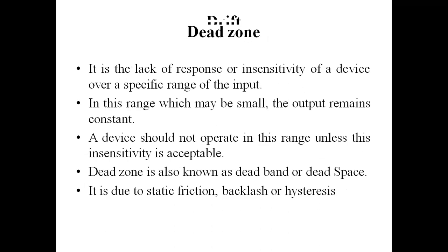The next one is the dead zone. What is dead zone? It is the lack of response or insensitivity of a device over a specific range of the input. In this range, which may be small, the output remains constant. A device should not operate in this range unless this insensitivity is acceptable. A dead zone is also known as dead band or dead space. It is due to static friction, backlash, or hysteresis.